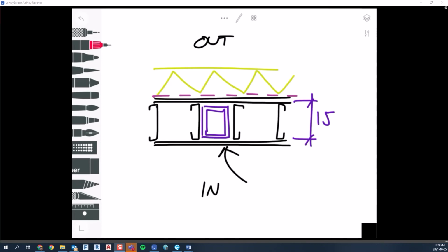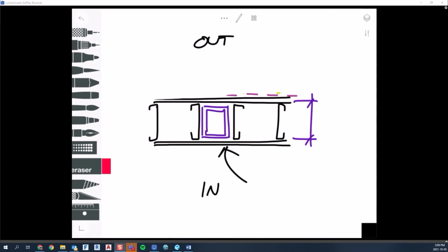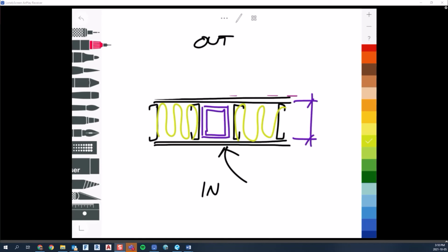Something else to consider too. Again, I don't really want to get into the science behind this right now, but one thing you don't want to do with an infill stud situation is put your insulation in the stud space. That's terrible, right? Think about why. You would have hardly any insulation around the column, so a lot of heat loss there.